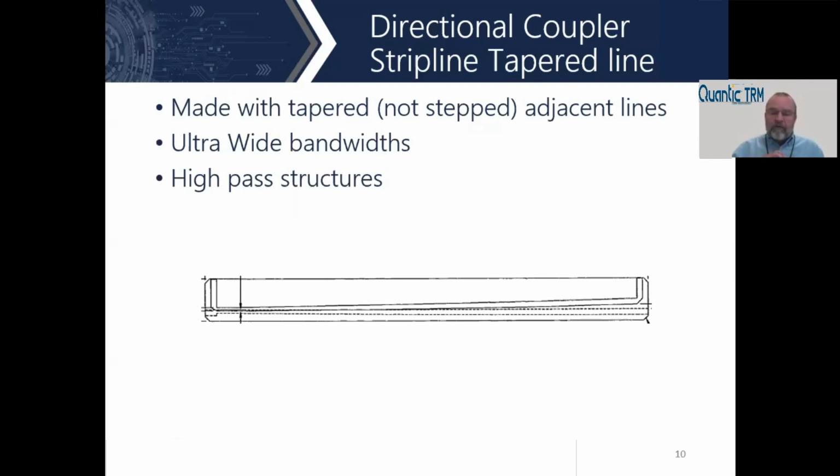Topic for another talk. But basically, this will continue to operate at higher and higher frequencies, and essentially has no theoretical upper limit mathematically. What limits the upper limit in reality has to do with whether or not the cavity that this is put into generates higher order modes, or there is some other kind of crosstalk between the connectors, the cavity, and the strip line. These are ultra broadband as far as the way that these are actually realized. Tremendous bandwidths are available for these sorts of structures.